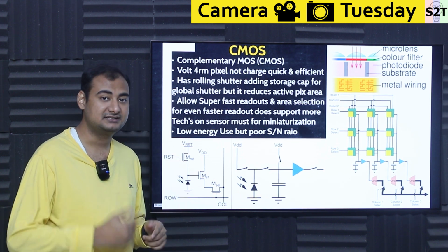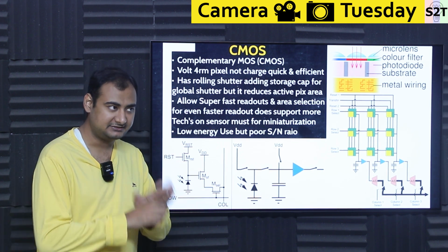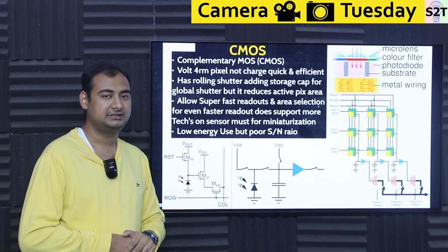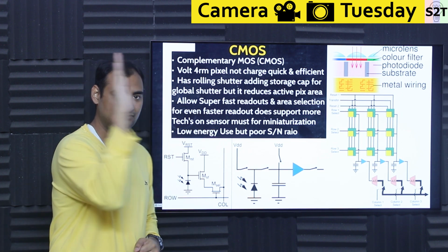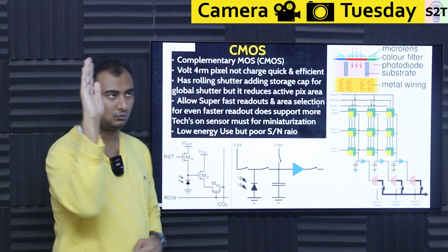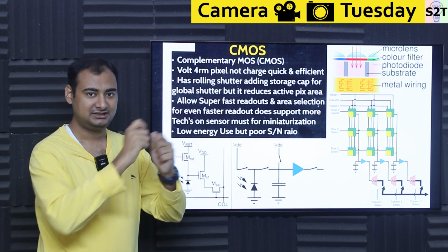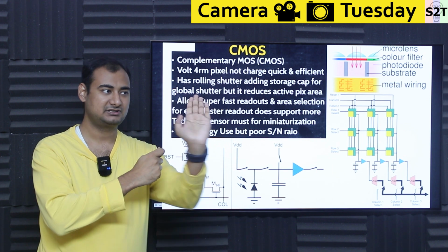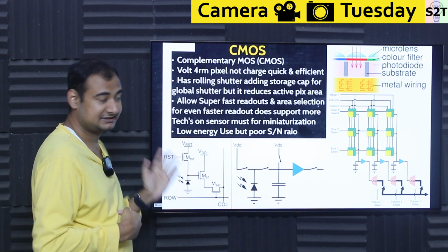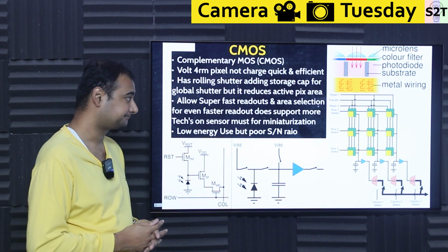Because of this many steps, it does have what we call rolling shutter. It literally reads row by row. So it creates a scenario where, if you're moving something fast, it's supposed to look like this, but instead it will look like whoo. Even on a small sensor, especially if you're on a fast train, you look at a mobile phone, if you see electrical poles, they will literally look bent. So that's the reason: rolling shutter.